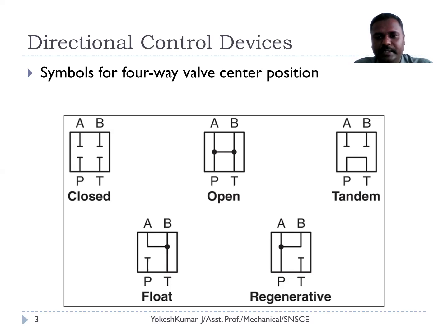If it is not properly used, it creates excessive pressure and finally tends to burst the tube, which leads to an accident. We use this tandem center so that the oil from the pump is pumped back to the tank, because the pump port is connected to the tank or reservoir, which will reduce the operation of the pressure relief valve. If at all we are not using a pressure relief valve, this comes into operation, where the pump port is connected to the tank port.